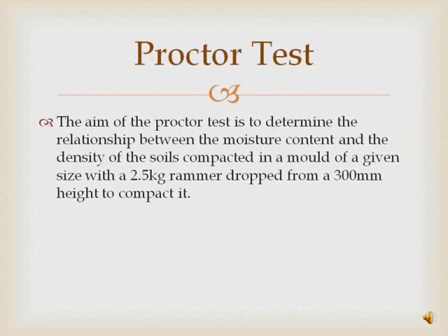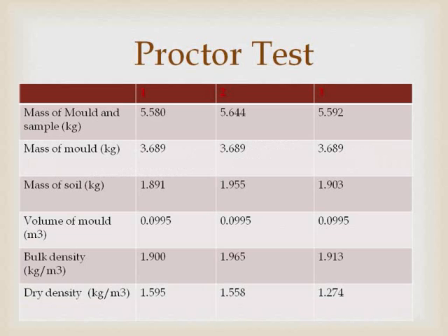The aim of the Proctor test is to determine the relationship between the moisture content and the density of the soils compacted in a mould of a given size with a 2.5 kg rammer dropped from a 300 mm height to compact it.